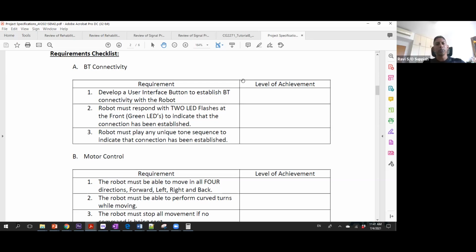No, I don't think you should be doing that, because the whole idea of the thread flag is you wait for the flag to be set. So you can either wait for individual flags to be set, or under the attributes you can say flags all or flags any, correct? So you can choose to configure your task based on which flags to be set, and then you execute. Correct.